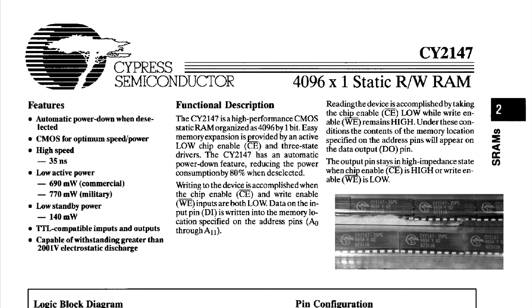Error correction. You see, that would be violating the KISS principle. But the other thing is that these 2147s have a separate data in and data out line, whereas on those more modern chips, there's a single data bus. And for this stupid design, as it is designed, the separate input and output lines are more appropriate, work better. So that keeps it simple and stupid.